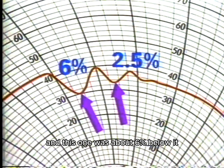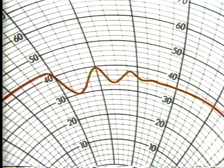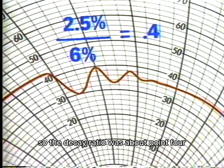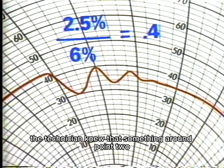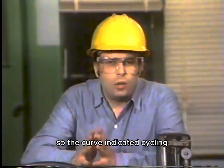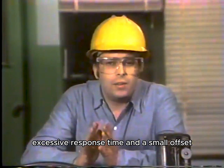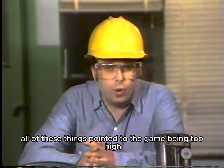And this one was about 6% below it. So the decay ratio was about 0.4, which was too high. The technician knew that something around 0.25 or 1/4 is what it should have been. So the curve indicated cycling, excessive response time, and a small offset. All of these things pointed to the gain being too high.